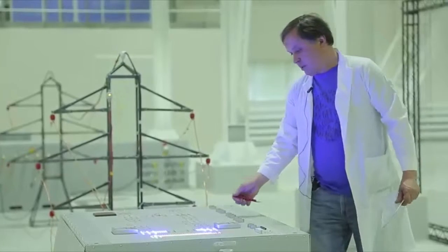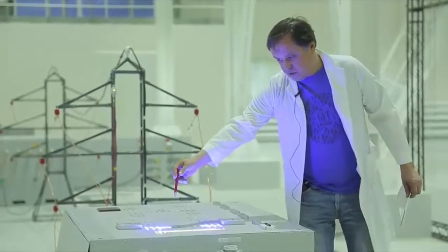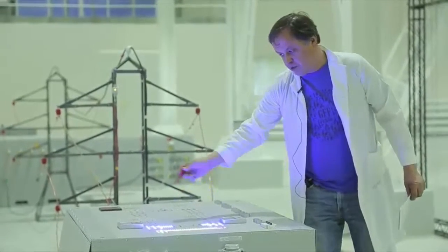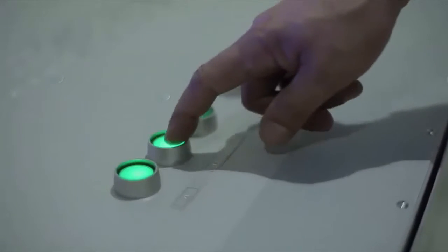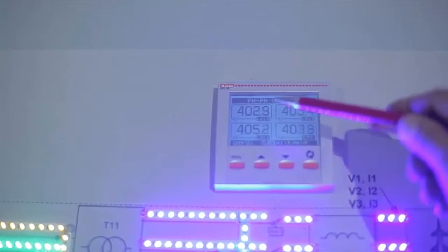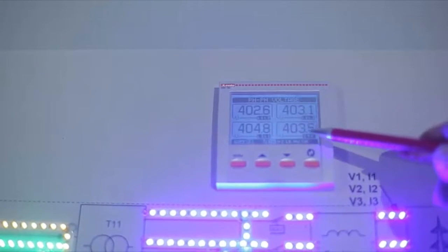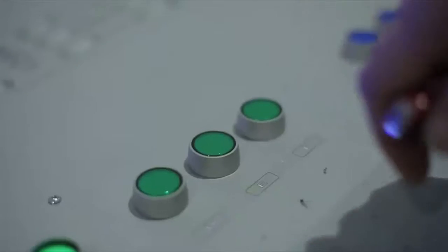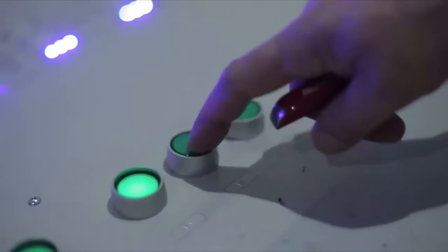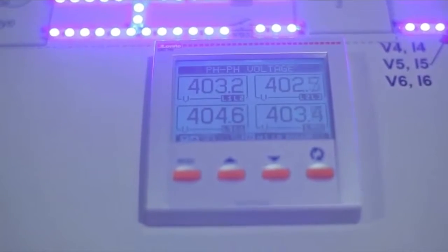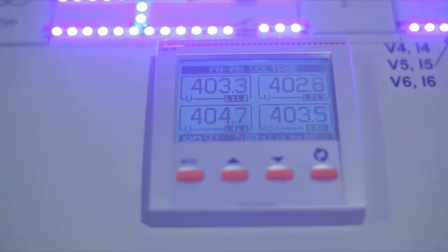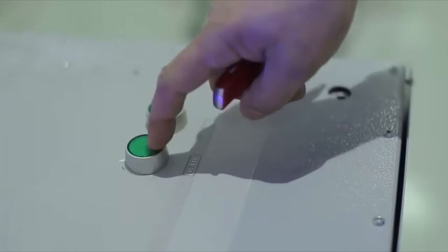Let us demonstrate operation of the line in normal 2-circuit 3-phase mode while supplying voltage to the line. As we see, the transformers are on. We apply voltage to phases A, B and C of the first 3-phase line, and we see 3 linear voltages at the first multimeter. Then we apply voltage to phases D, E and F of the second 3-phase line, and 3 linear voltages can be seen at the second multimeter.